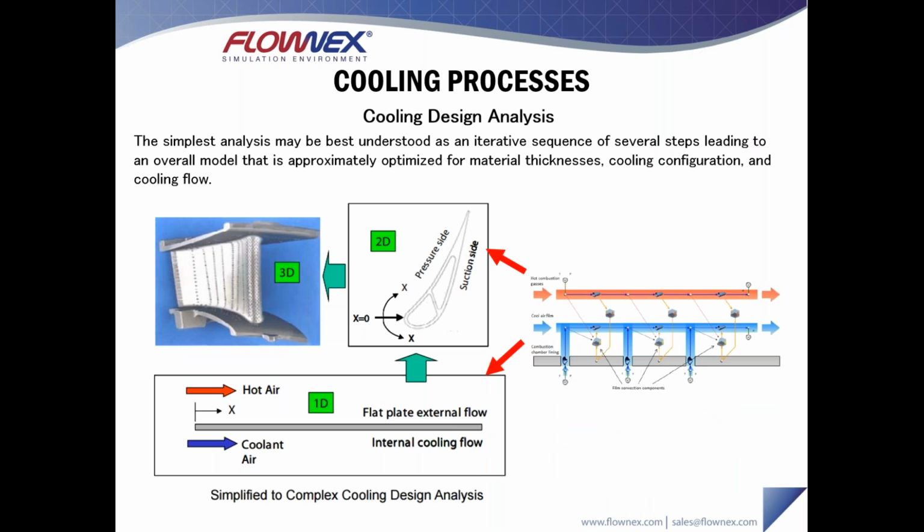So for the most part now, Flownex can be used not only for modeling just cold flow or airflow, but you can also integrate heat transfer modeling with your flow models, to do cooling design analysis. The simplest way cooling design analysis can be understood is an iterative sequence of several steps leading to an overall model that is optimized for things like material thickness, cooling configuration, cooling flow, and all of that.